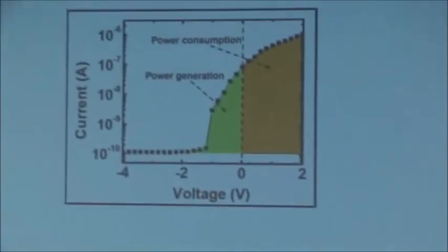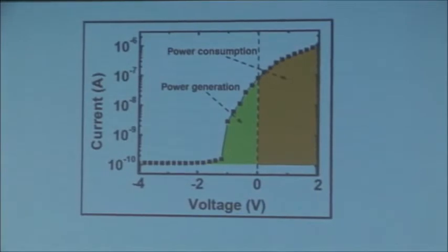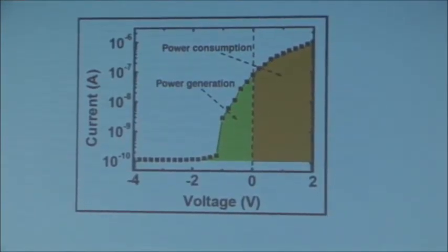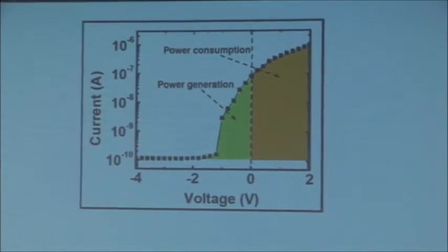But remember, we are measuring the current with very high accuracy here, on the order of a few tens of picoamps. So this is really not noise. It's actual power delivered. It's very low. But remember, thermionic emission is exponential. So if you manage to heat up the sample a little more, you could improve things dramatically.